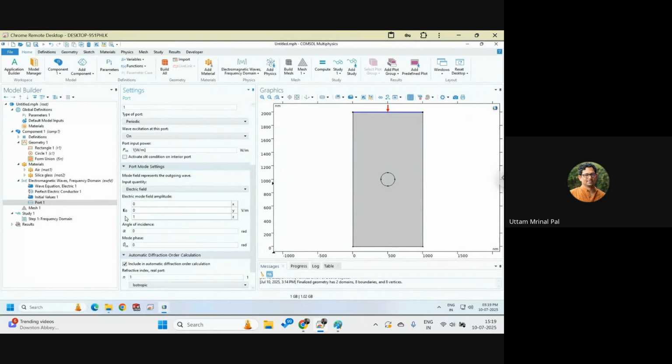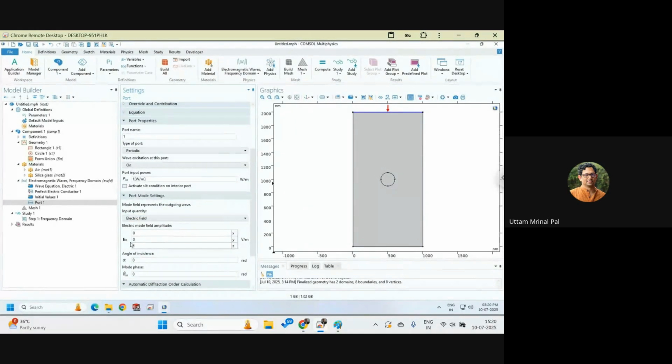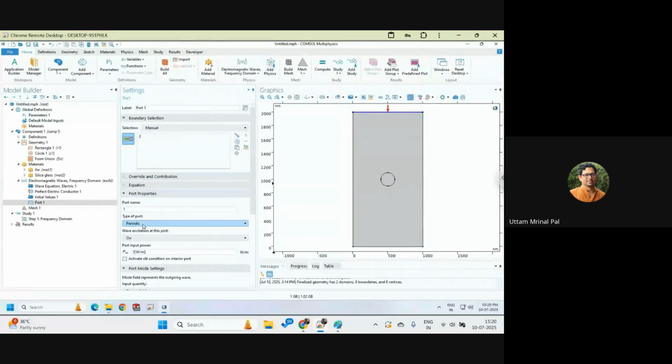Yeah, you can use S polarization as we have done in the first class. There are three sections: linear polarization, circular polarization, and user defined. If you put S polarized, it means out of plane, and this is the same as 0 0 1, the electric field.